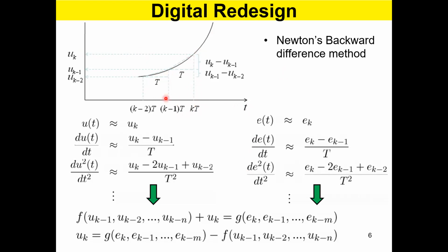A moment ago, it is k minus 1 times T, one sampling interval prior, and my controller should have given me uk minus 1. Another step behind, k minus 2 times T, the controller would have given me uk minus 2. This is how the controller should operate: every T time, it has to give out a control signal.